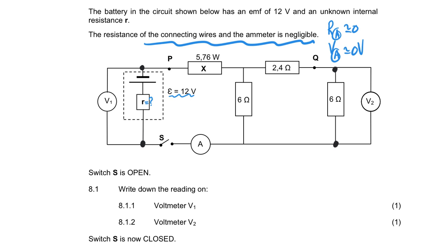So I'm going to use something called the Rails method, the Rails format, and that involves redrawing the circuit in a way that's going to be easier to interpret the voltage drops and the current splitting, and really does help you with voltages. Now, yes, it will take you maybe 1, 2, maybe 3 minutes to redraw, but I'm of the belief that that is a valuable investment.